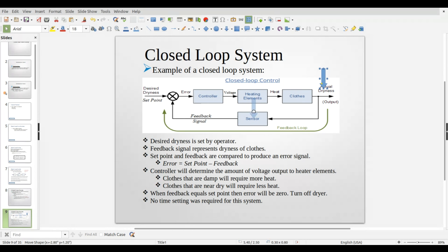All right, so we might use a delta T timer, kind of like we use for the integrator, and only do it once a minute or something, and make the adjustment. Or we may monitor it every scan of the PLC.